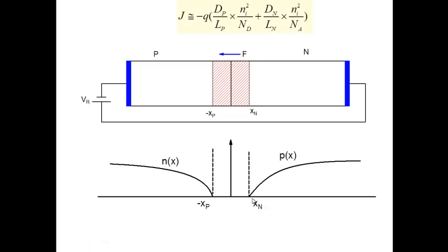So now, how does this current flow? We have said that this is the total reverse current. This part, as we said, originates from the N region, and this part originates from the P region here. So let's try and understand how this particular current really flows. And remember, in our derivation, we have said it's a diffusion current. All this minority carrier current is a diffusion current.